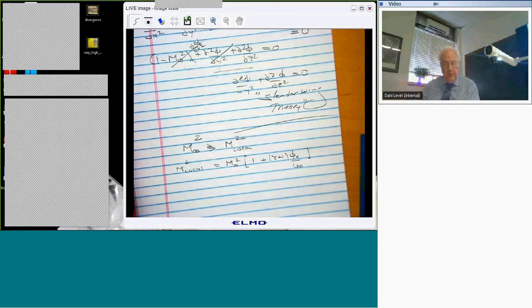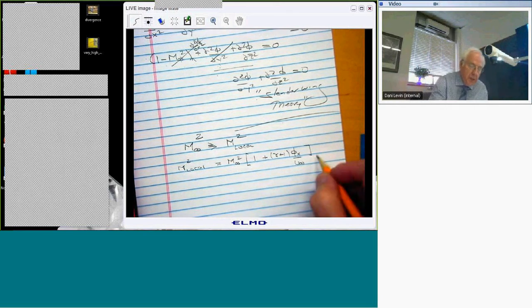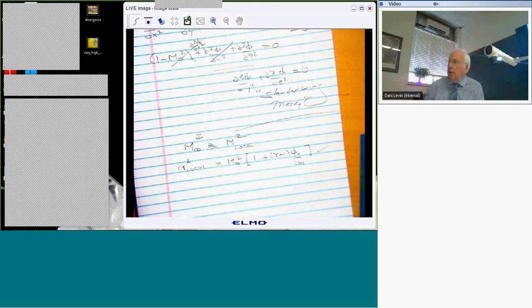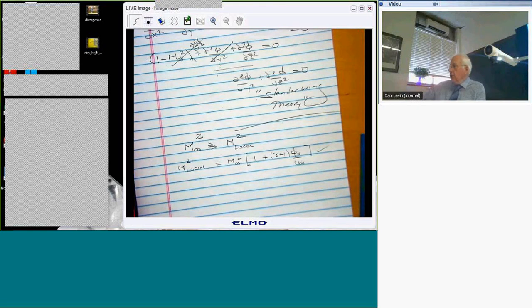Okay? So with this replacement in this equation, that's called transonic small disturbance theory. This is not the full nonlinear theory. The full nonlinear theory is much more elaborate and it's written down in the book. And people have written CFD codes, not so much anymore, but back in the day, to solve the full nonlinear potential flow equations.